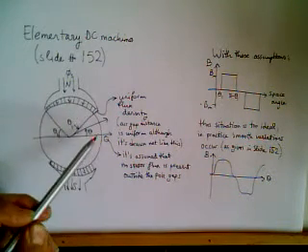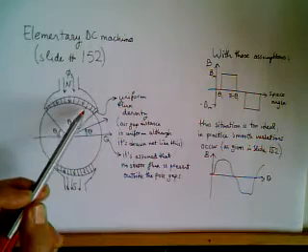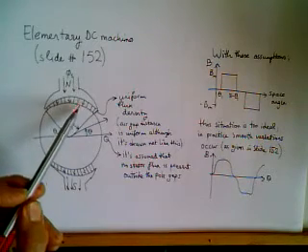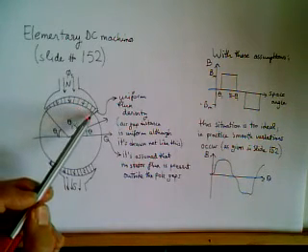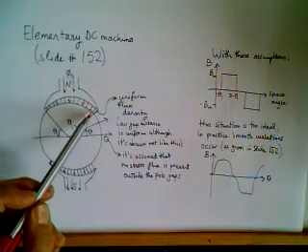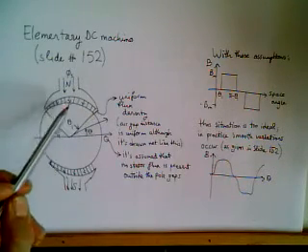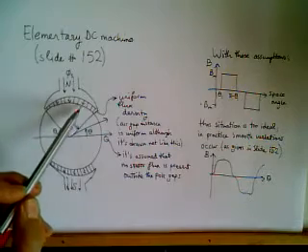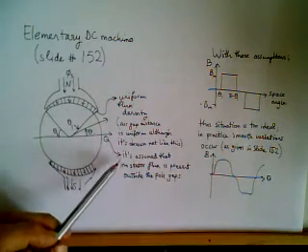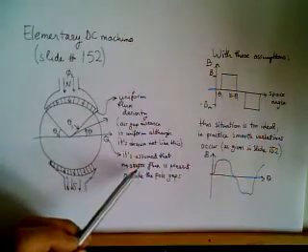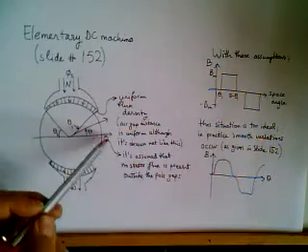It's always uniform, and this gap is very narrow, usually a fraction of or a maximum of a few millimeters, and all the electromechanical energy conversion occurs in the air gap. And outside, no stator flux is present outside the poles.